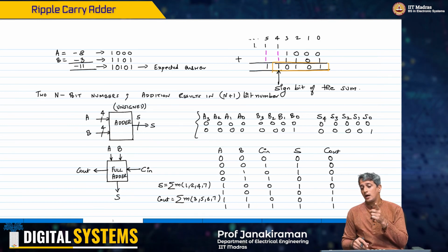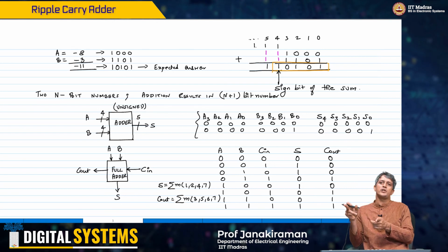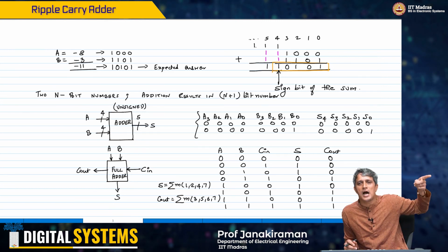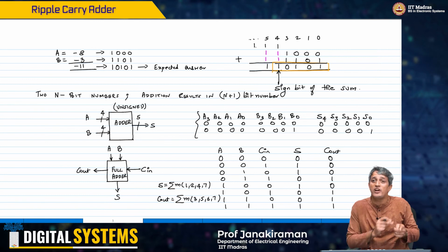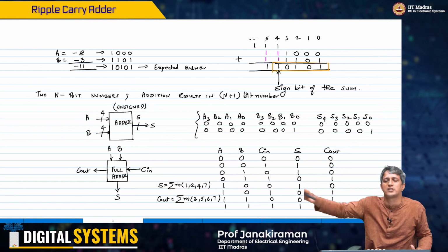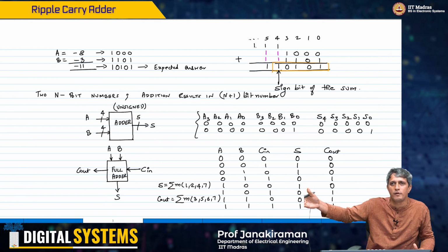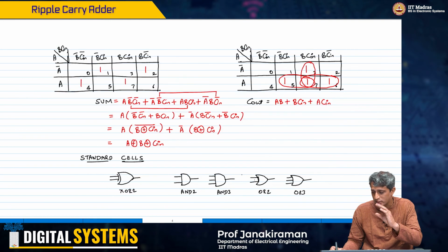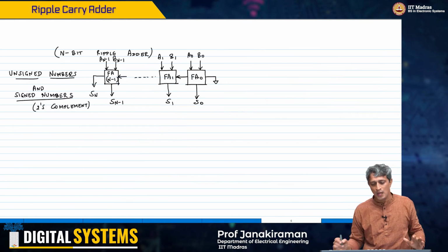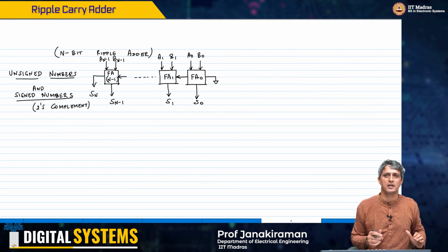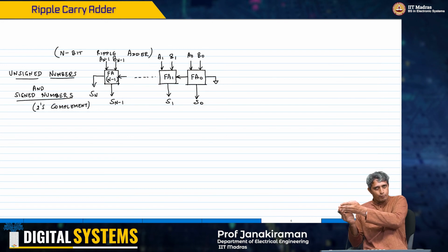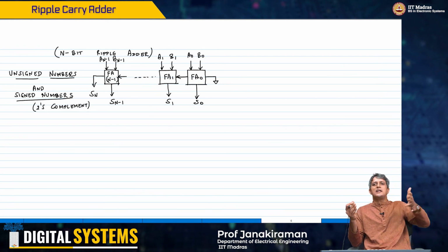However, S1, the sum 1 bit, is indeed determined by A0 and B0 because that depends on the carry. Like this you can keep going, the highest bit Sn minus 1 will depend indeed on all possible bits that are there before it. So that's why this is actually a very complicated implementation to get directly. But what we have done here is, we evaluate for A0, B0 and then propagate that carry through in a step-by-step fashion.